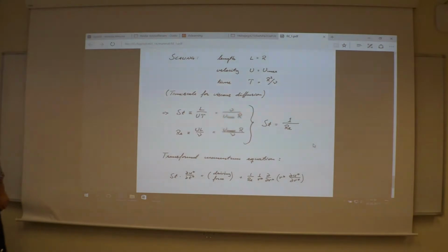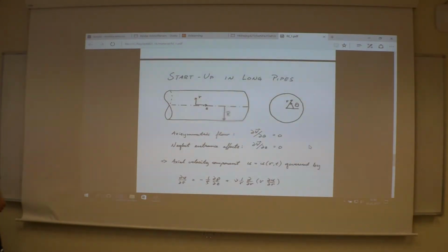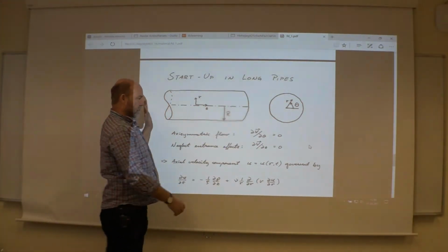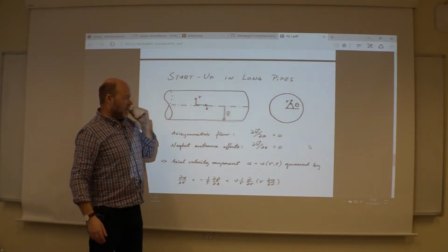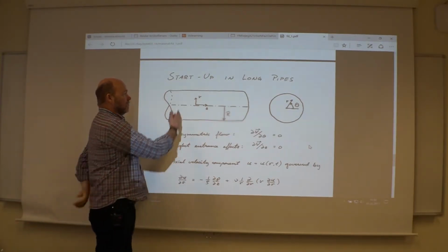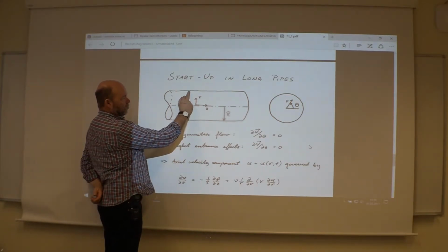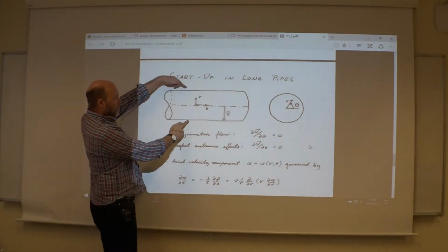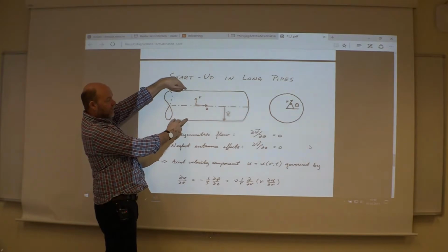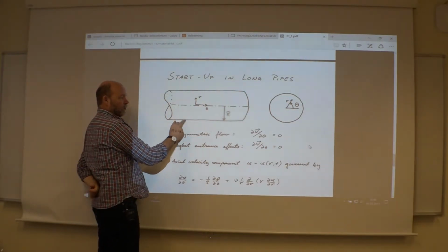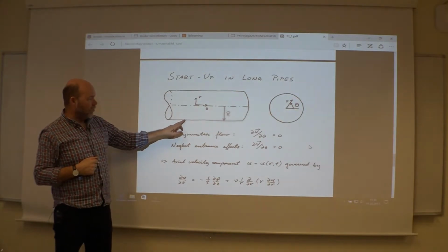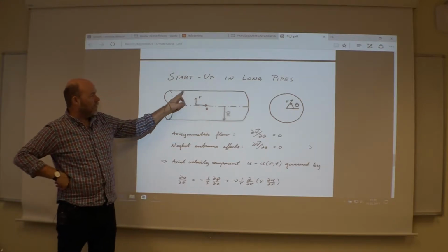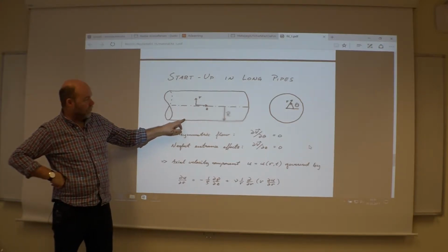And if you look at the problem, everything equal to 0, and then all of a sudden you switch on a driving force. So it's beginning to move. So say the first tiny little motion for a cross section will be a very small velocity, fairly constant over the entire cross section, except you have the boundary conditions on the wall, no slip condition. So there you have 0. So it will be close to a singularity, close to the wall. So of course in the further development you're going to get the parabola, but still 0 velocity on the wall.